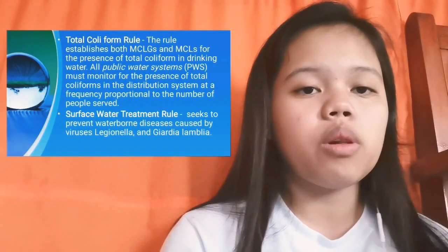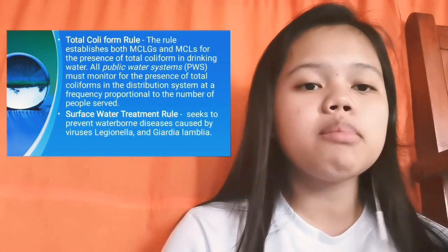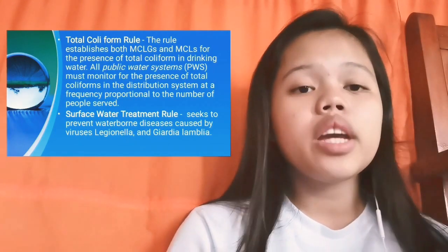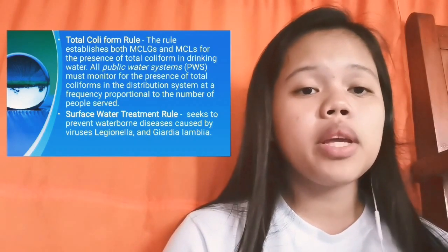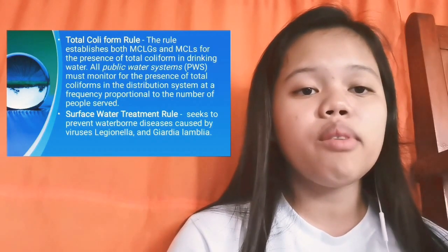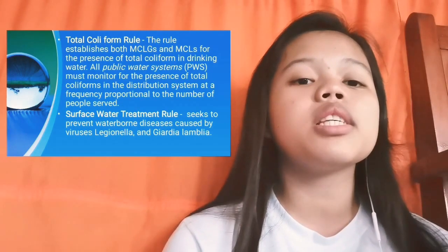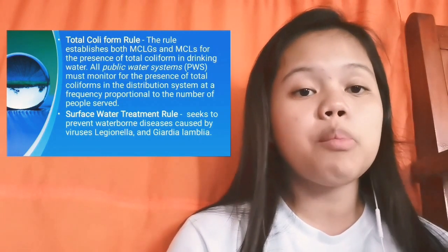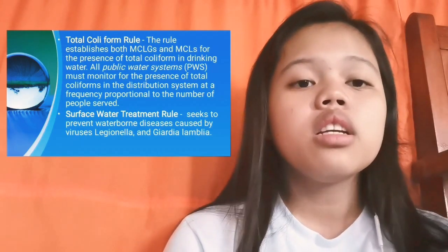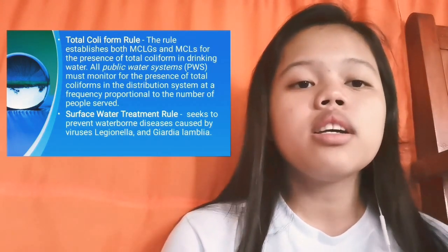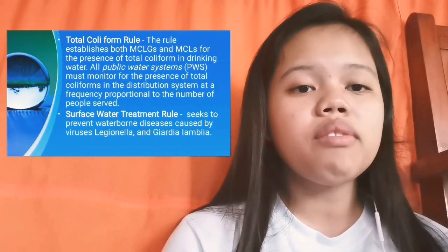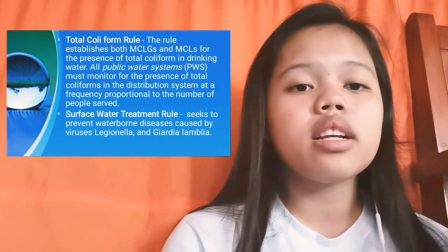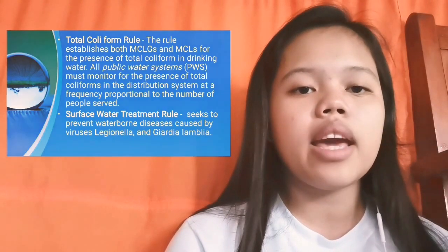Total Coliform Rule. The rule establishes both MCLGs and MCLs for the presence of total coliform in drinking water. All public water systems must monitor for the presence of total coliforms in the distribution system at a frequency proportional to the number of people served. Surface Water Treatment Rule seeks to prevent waterborne diseases caused by viruses, Legionella, and Giardia lamblia.